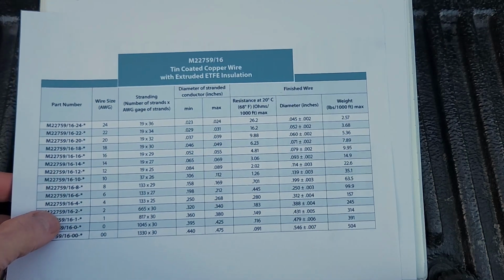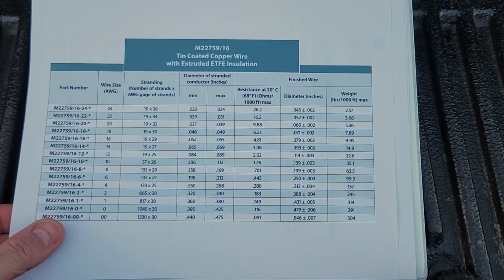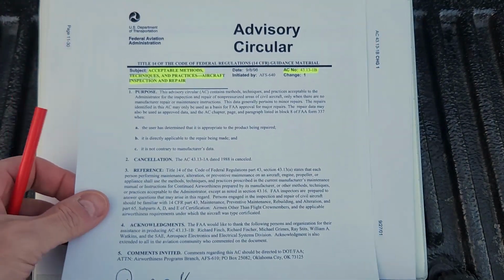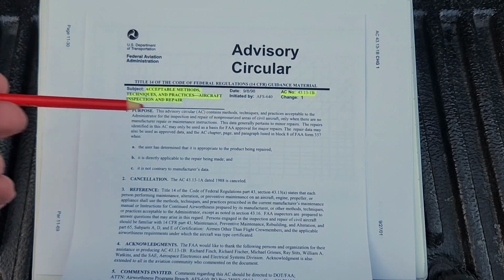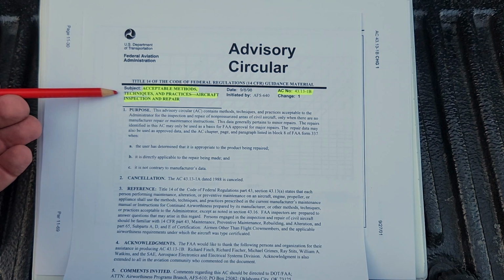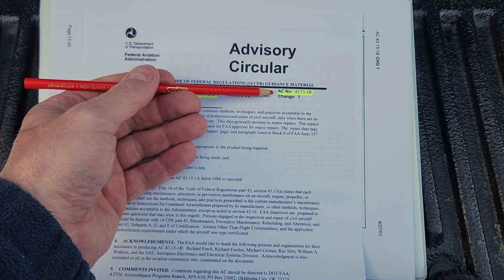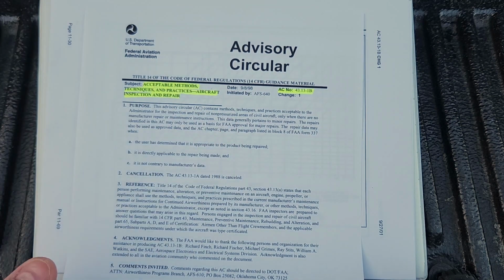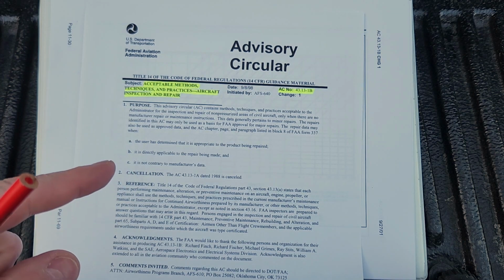There are pre-calculated tables that take Ohm's law into account. One of those tables comes from the FAA for aircraft. So the FAA published these things called advisory circulars. This one's acceptable methods, techniques, and practices for aircraft inspection and repair. The AC number is 43.13-1B. And some of these advisory circulars are like one page long. This one is like a 1.5 inch thick printed book.